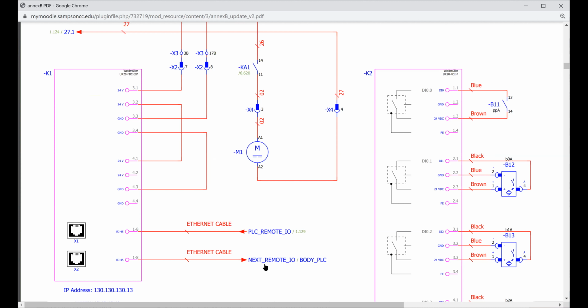So I've got an Ethernet switch over here, and all that goes into a switch over here. That switch feeds into one port on the first PLC. And that PLC then connects to the remote I/O, and then it jumps all the way through. So from that one switch, with our 7 laptops hooked up, you can access any PLC you want at any time from any computer.